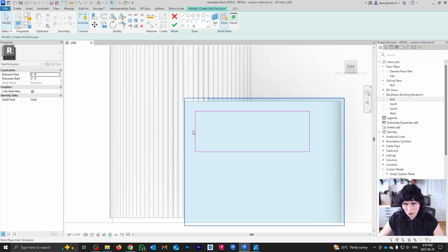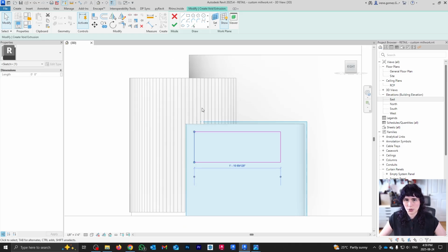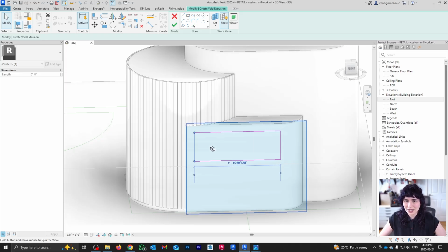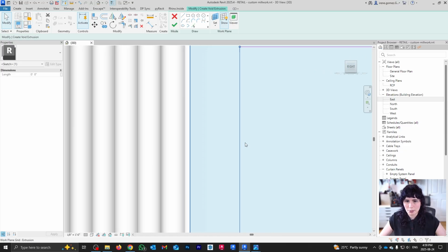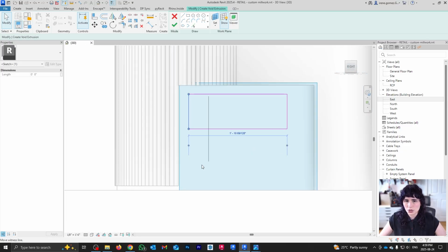Yes. Okay, that looks about right. Here, it's not giving me the temporary dimension for this because remember, we kind of had them merged together. So it doesn't really know where I would want it to snap into. Keep that into consideration. Sometimes when you merge geometry, it can create situations where Revit doesn't know how you want the interactions to go, but you can move your temporary dimensions to help Revit understand.